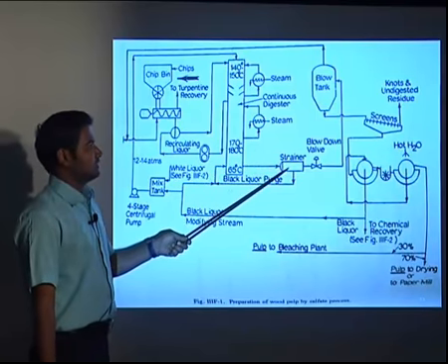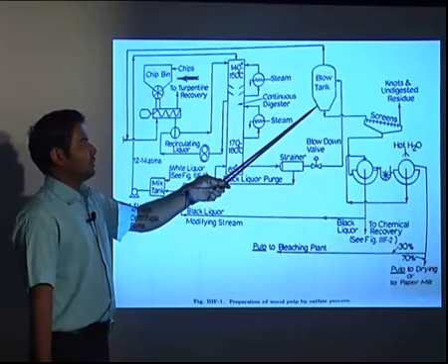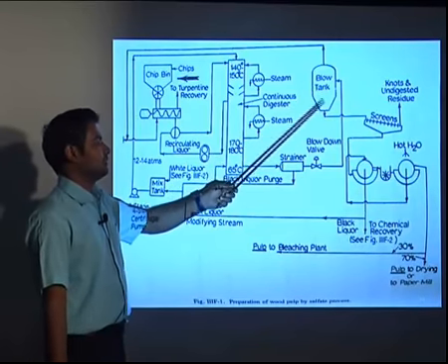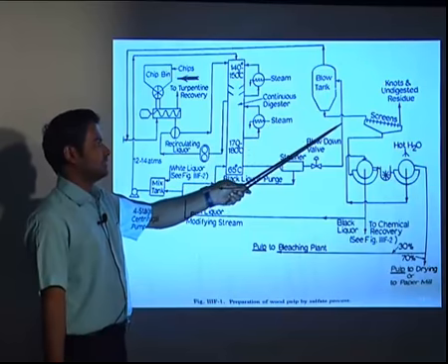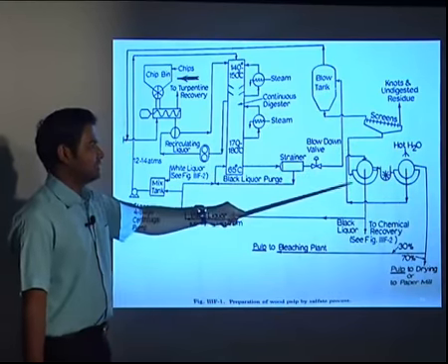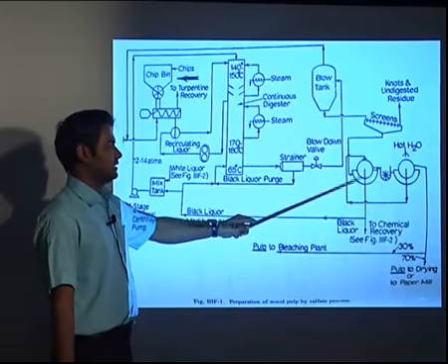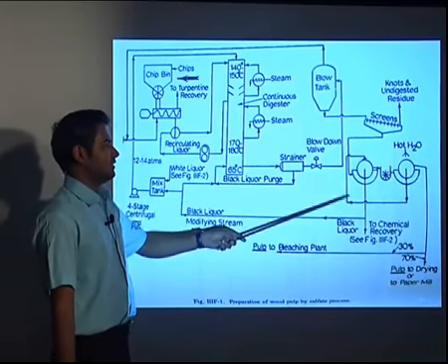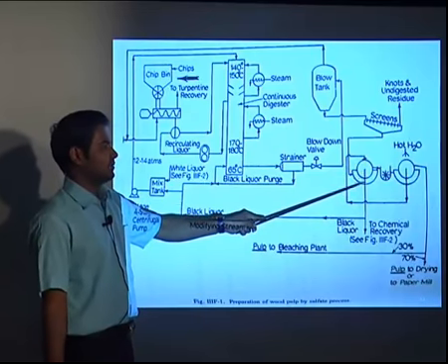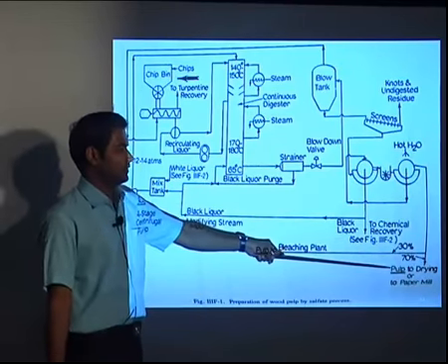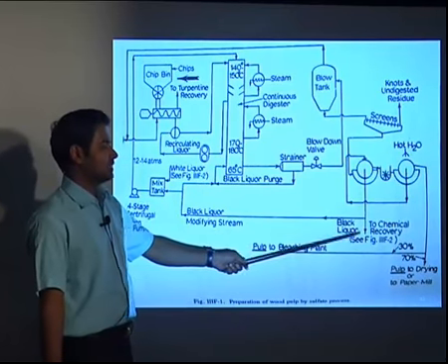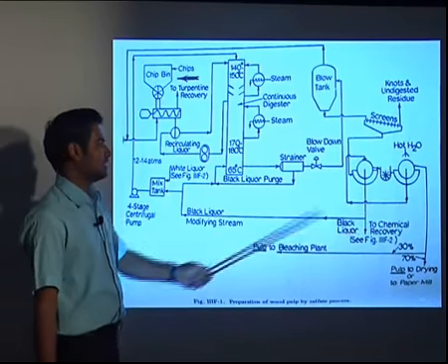That will come into the strainer, and in the blow tank it will be blown. Here the water will be separated from the cellulosic material. Then in screens it will be screened, and through the rotary mixer we can add the chemicals, and we can have the pulp for drying. After the pressing of the pulp, we can have the pulp for drying, and the filtrate which contains chemicals will go to chemical recovery.